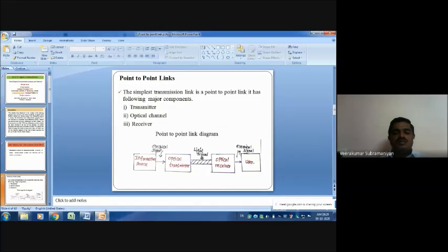We can select any one of these three components. They take care of the detection process, the responsivity and sensitivity, and can also identify the presence of noise. According to that, it chooses certain algorithmic processes to overcome the losses present in the light signal. Then filtering is used to remove unwanted noise, and pulse reshaping is also taken care of by the optical receiver unit.